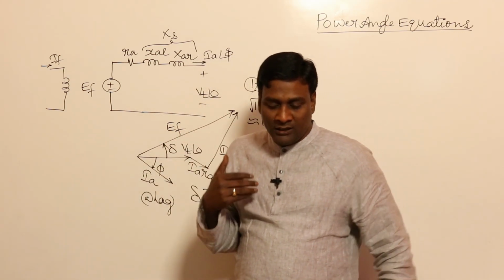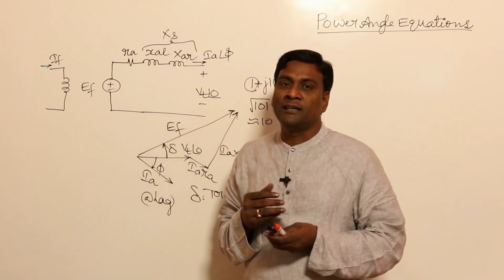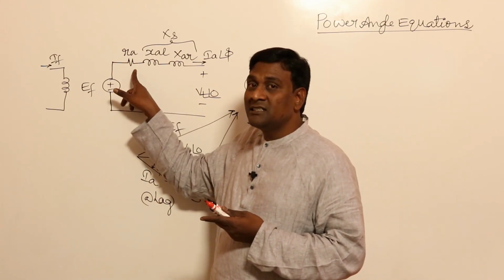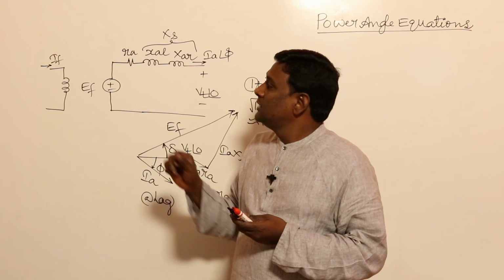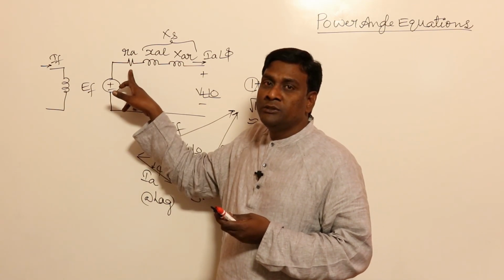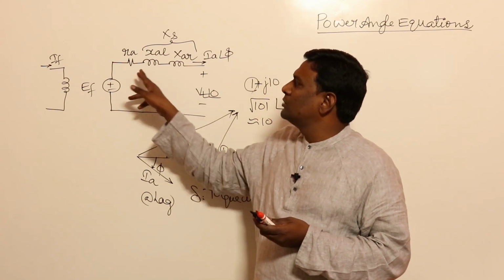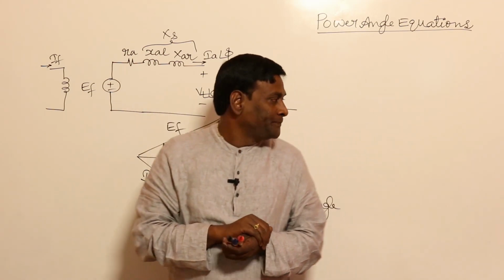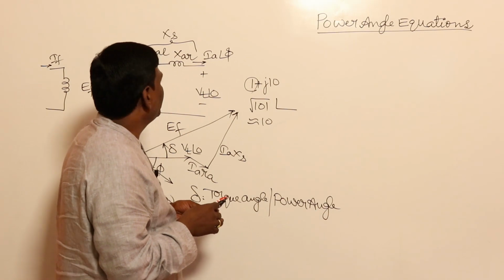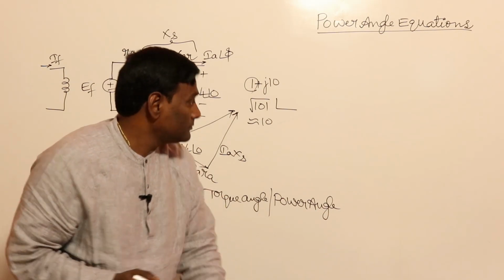From the cooling point of view, like temperature rise, armature resistance will be considered in practical conditions, and in finding efficiency as well. Except for these two, normally in practical conditions armature resistance will be neglected.